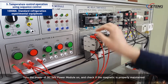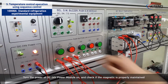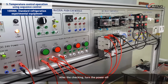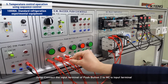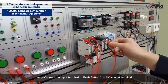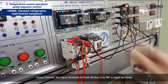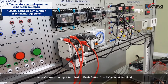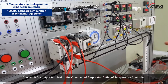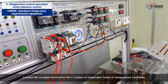Turn the power of DC 24-volt power module on and check if the magnetic contactor is properly maintained. After the checking, turn the power off. Jump connect the input terminal of push button 2 to MCA input terminal. Connect MCA output terminal to the C contact of evaporator outlet of temperature controller.